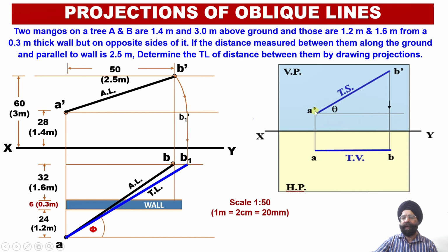So now here we have got the plan projection AB, but this plan projection happens to be inclined to the vertical plane. So we have to rotate this black plan projection line AB so that the AB projection becomes parallel to the vertical plane.